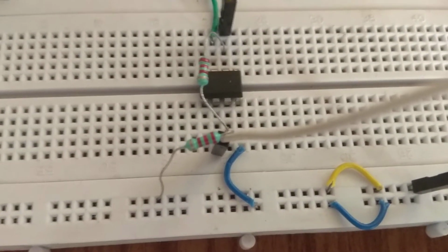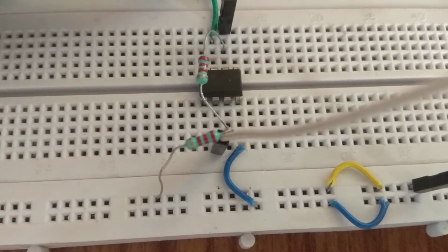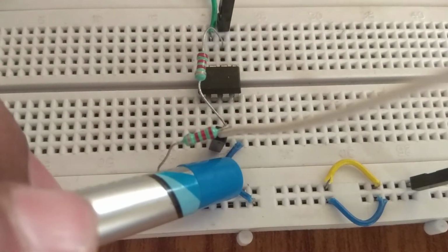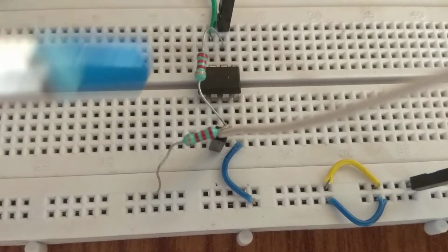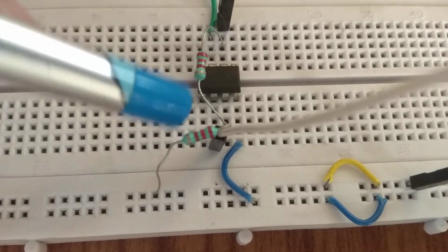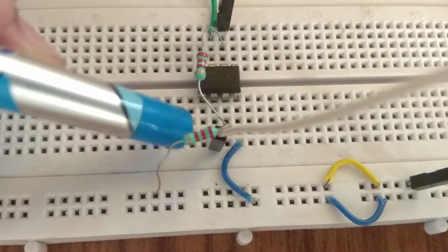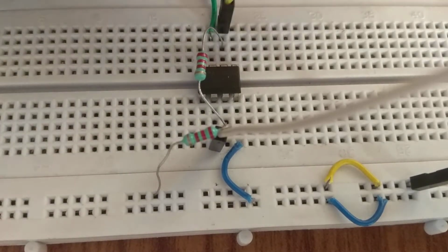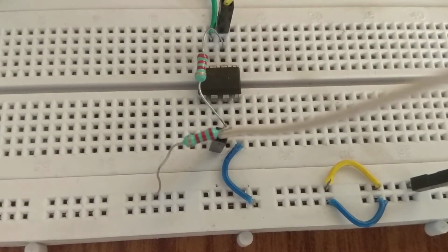Now if you look at the circuit, this is the biasing we have done. This is the positive biasing that we are providing with the green wire. The blue wire provides the negative biasing, and R1 and R2 we have connected the same, around 2.2 kilo ohm. This white wire is giving the input at terminal 2, and from this yellow wire we are taking the output. Now let us zoom to the DSO.